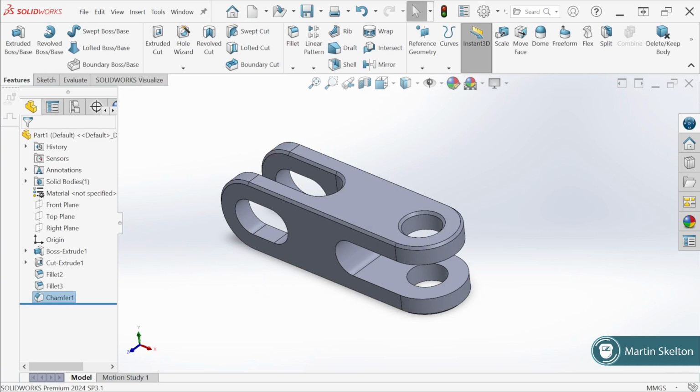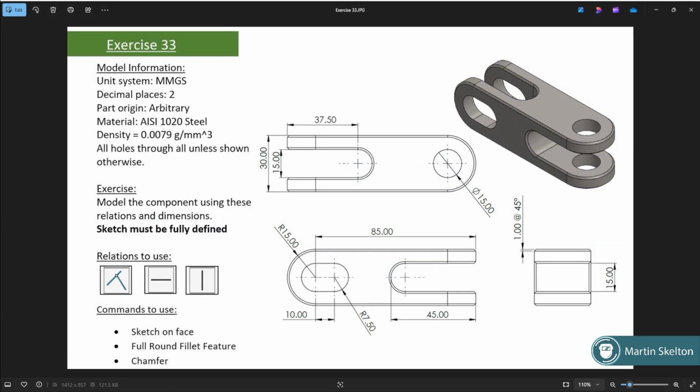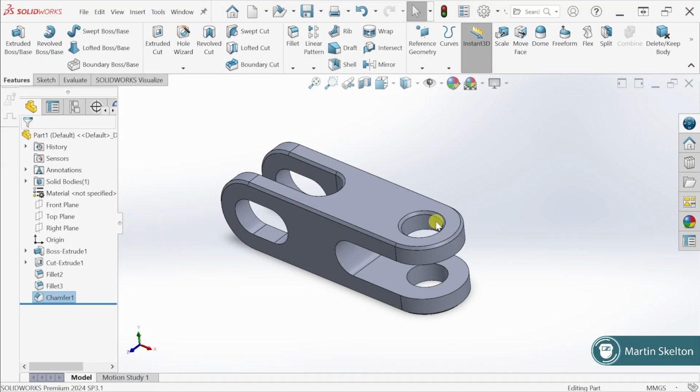Wait there, I just want to go back and look at my image again. If you look at our image, we can see that this circle is not filleted. So be careful if you're putting in fillets or chamfers that you don't just click on a face and say, yes, it's done, because technically it is not correct. Oftentimes you get away with using it. It's a very fast thing to do. Click and it'll select all the edges for you, but just make sure things like holes not requiring a chamfer or fillet don't get chamfered.